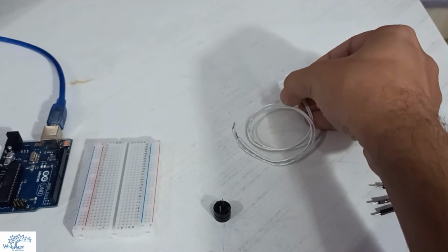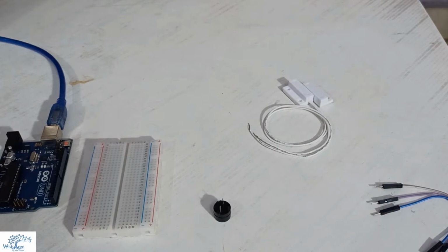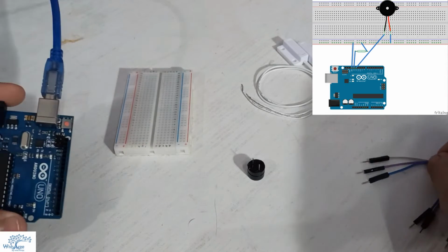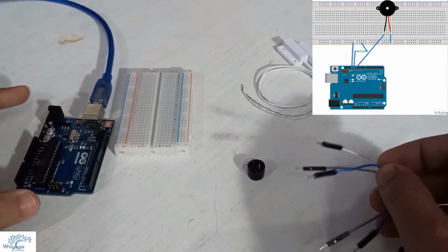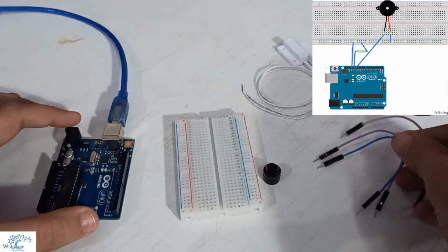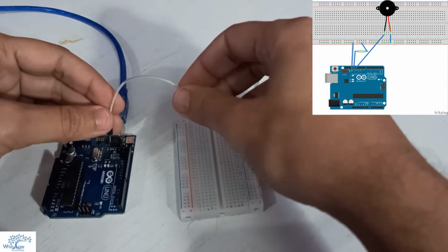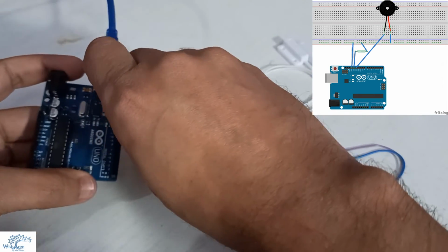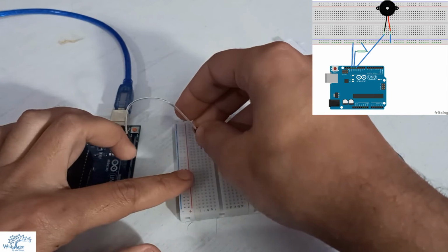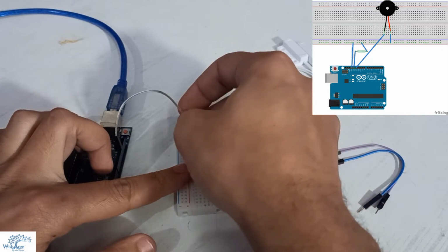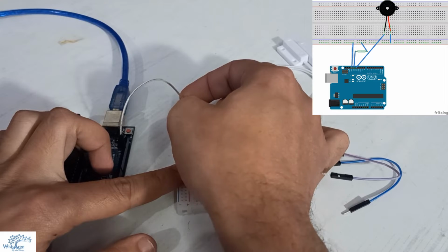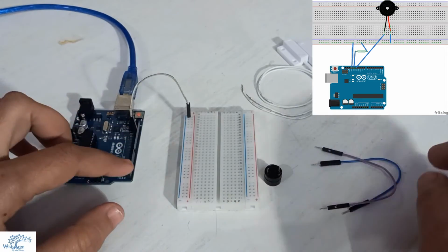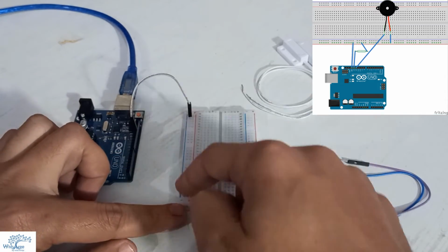Okay, so let's begin and build our circuit. If you look at the circuit diagram or the schematic, then based on the schematic, we will first connect the ground pin to our breadboard. Here our breadboard has negative line, which is highlighted in blue. We'll connect the other end of the ground to the blue line. So now this complete rail is negative.